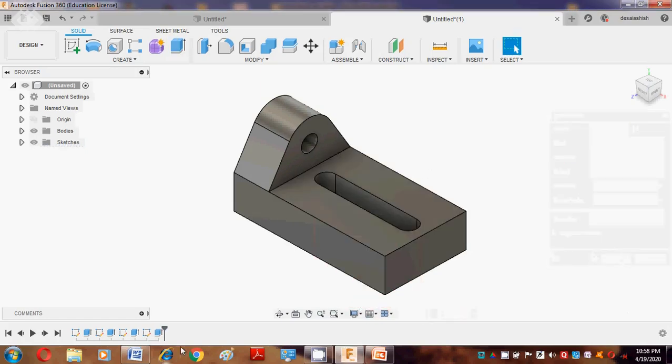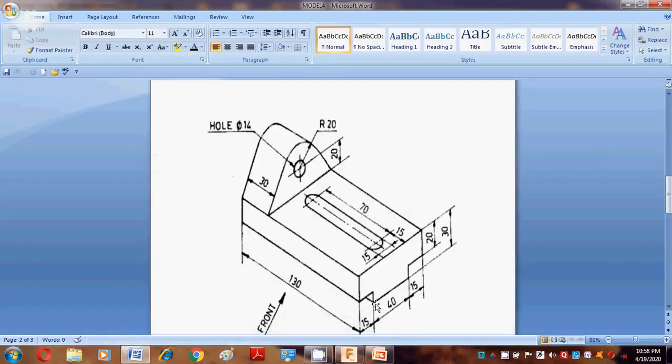So this is the job. Now we move for this profile. For preparing this profile, we require this 50 mm length and height is 10 mm, because 30 minus 20, so that becomes 10. So this is 10 by 15, so we can make a rectangle of 10 by 15 on both sides and then extrude in a negative direction. So this is how we make the profile.